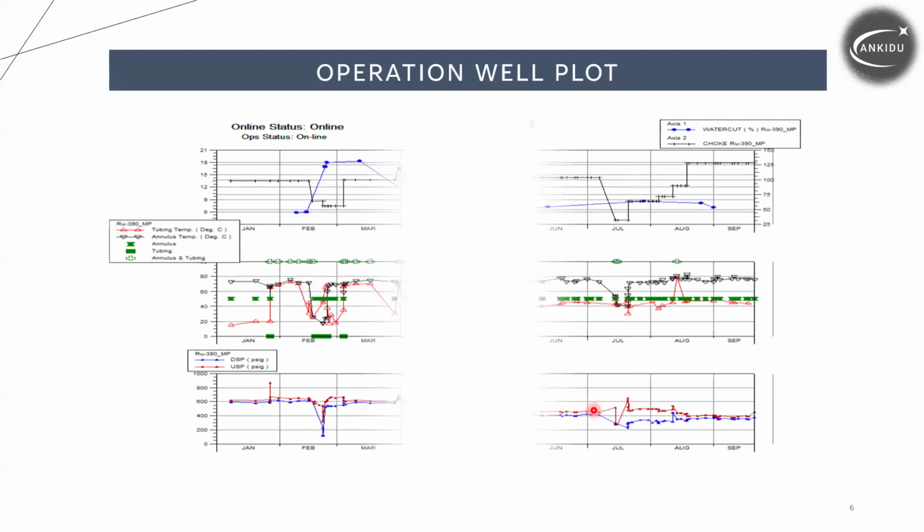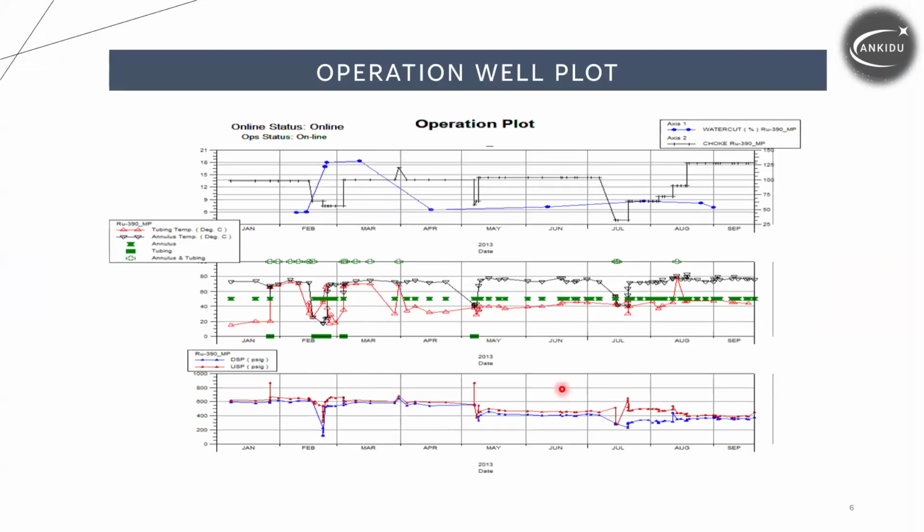Okay, let's check now our wells. What is happening? Why are those wells not going back again? So data review and history matching is an essential part of our well files. We need to check the production history, reservoir performance, well integrity, to what? To identify the reason for cessation. Is there any water breakthrough, gas breakthrough? Is there any sand or mechanical failure? Do we have any formation damage? Do we do any shut-in because of economic factors?